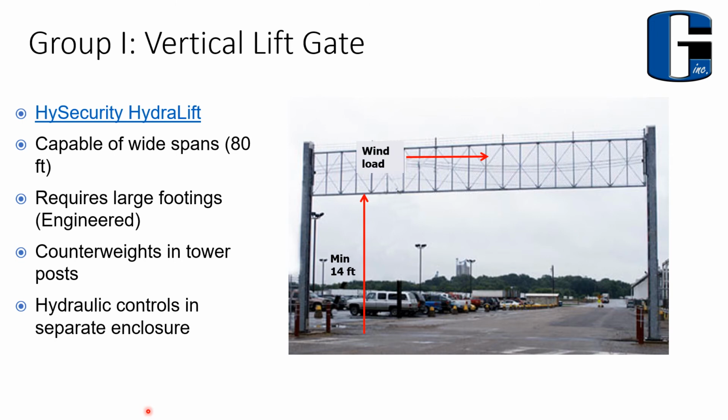Now you do want to consider wind loads. When that panel is up there in the air and you have a lot of wind or gusts of wind, the footings and the concrete down below need to be substantial, often requiring the use of an engineer or a soils engineer to verify the footing size given the kind of soils and the kind of wind areas.